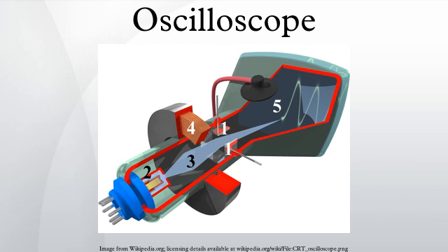Digital oscilloscopes. While analog devices make use of continually varying voltages, digital devices employ binary numbers which correspond to samples of the voltage. In the case of digital oscilloscopes, an analog-to-digital converter is used to change the measured voltages into digital information. The digital storage oscilloscope, or DSO for short, is now the preferred type for most industrial applications, although simple analog CROs are still used by hobbyists.